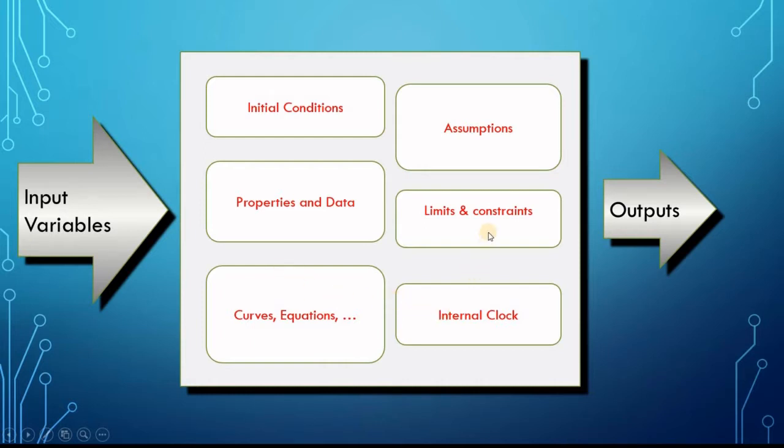Then what are my assumptions? I have to make some assumptions. Let's say that for a tank, your level will never be below zero and it will never go beyond the overflow pipe, meaning your overflow pipe is big enough to take all your inputs with no output at all. All the flow rates in the tank will go through this pipe and it will never exceed the level of the overflow. And then we'll think about all the limits and constraints which you can implement in your design.